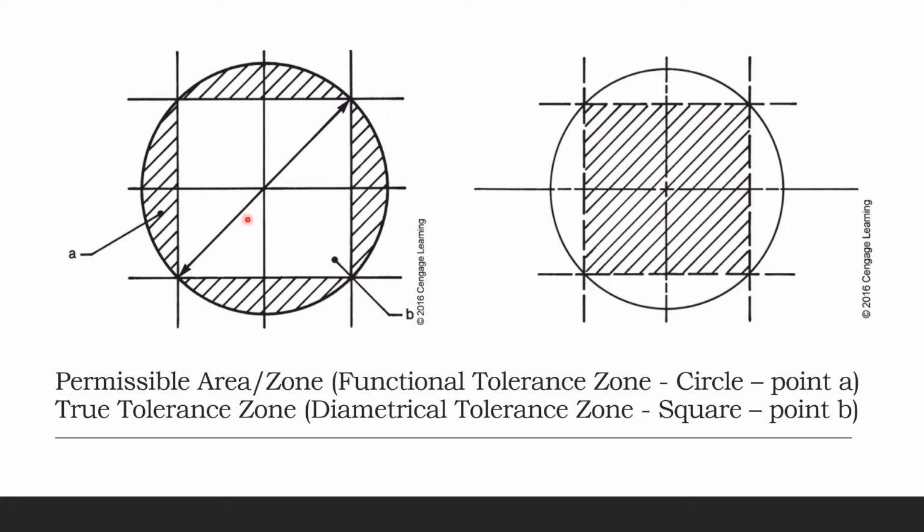Meaning your drill can go here, and here, and there. This is very exaggerated, okay? It's only a 1 millimeter size, it's pretty small. So when you drill it, sometimes that diameter will come off of this area and land here or here or here. That's all right, okay? Why? Because it is still functional, and the product will not get affected. If your drill point goes off from here to here, that's fine. So therefore we call this area the permissible area.